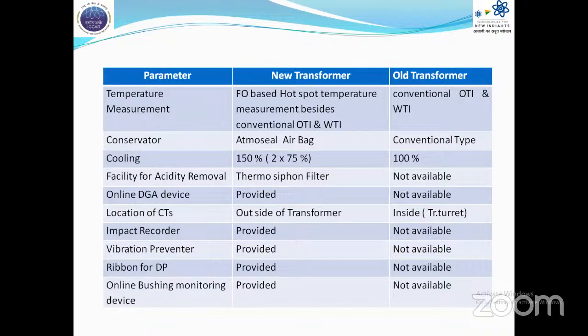The release of gas and the rate of rise of gas depend mainly upon the severity of the fault and the seat of the fault. So DGA is an effective tool to detect the gases and their concentrations, so that very advanced alarm signals can be given and corresponding maintenance programs can be planned. But in older transformers, DGA has to be done every 6 months or 1 year, depending upon the maintenance schedule of the transformer.